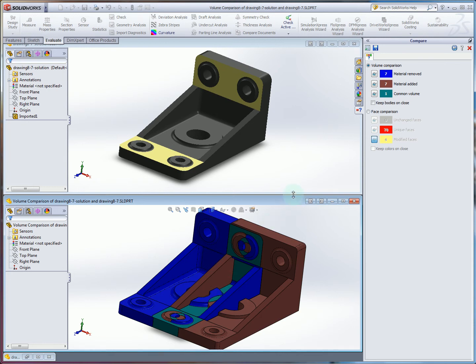So there are a couple ways to go about this to make coordinate systems that match up. You can make an assembly and have them shift over, but in my experience, I think the easiest way to go about it is to just make two coordinate systems, one in each part, that are easy to draw and easy to mentally picture the orientation of. So what do I mean by that?